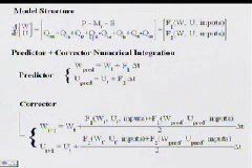So this just shows the numerical modeling structure of the model. And here basically it says we're looking at how the snow water equivalent and the energy content of the snow change with time. And snow water equivalent changes with precipitation, melt rate, and evaporation. Basically, this equation says that the rate of change in time of the snow water equivalent is equal to the precipitation minus the melt rate minus the evaporation. Precipitation adds to the snowpack; melt, outflow, and sublimation take away from the snowpack.